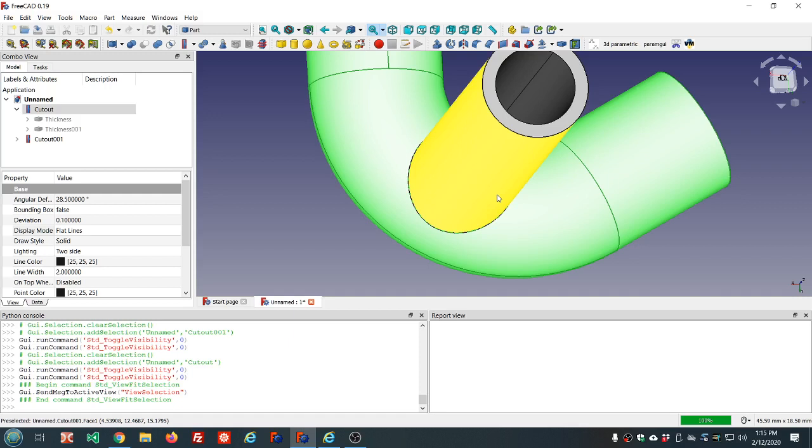Now, I use ABS printing on my 3D printer with the ABS filament. The acetone, which is basically fingernail polish remover, works as a solvent for ABS, and it's a really terrific glue. So even if I have two parts that are exactly the same size, when I put a little bit of that acetone on there, it dissolves it a little bit, and it'll actually fit. So if I were making this for some project, I would just leave it the same exact size and glue it in with acetone, and it would fit.